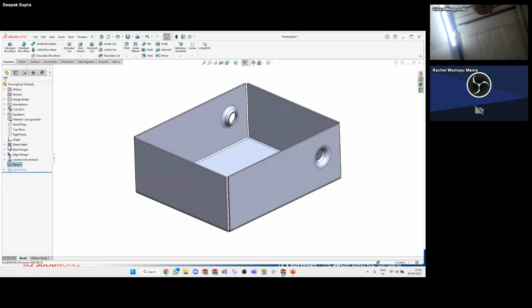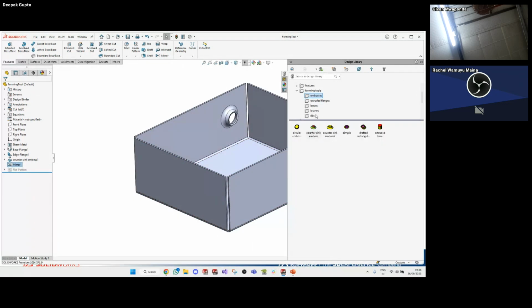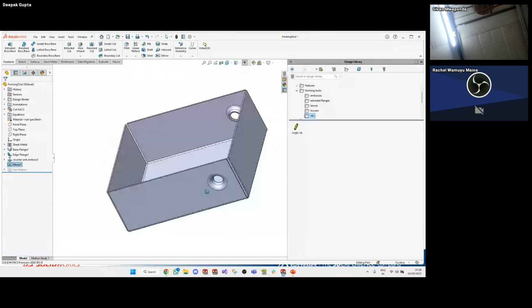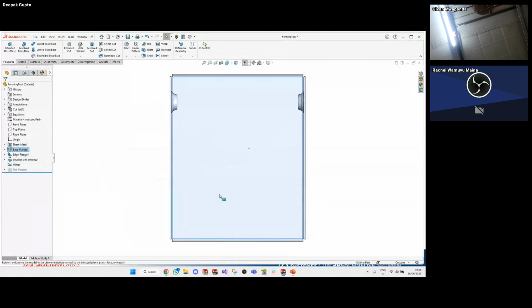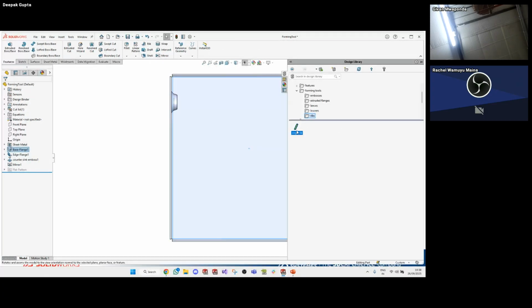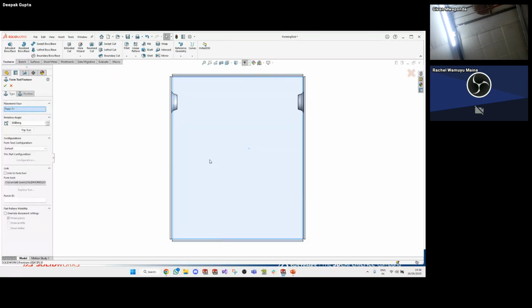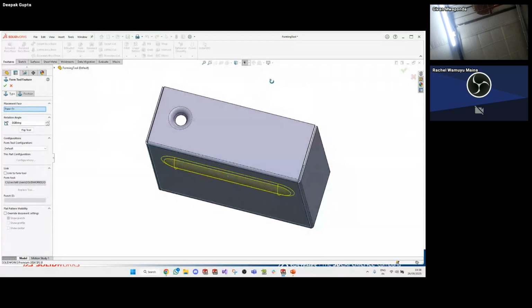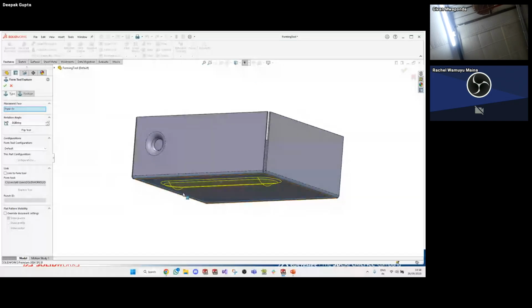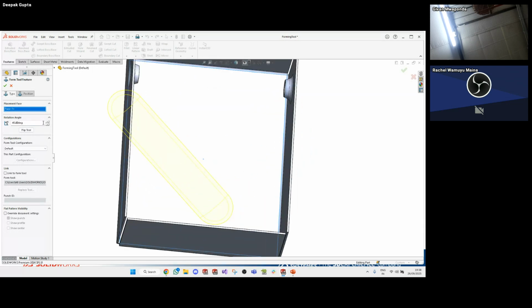Let's look at one more forming tool. So let's look at rib. So say we want to add some strength to this particular area, not using the cross break because it is not a thin part, but we'll add some ribs. It's a very huge rib, but we can change the direction, and like we're saying, we can change the angle as well. Let's make it 30.